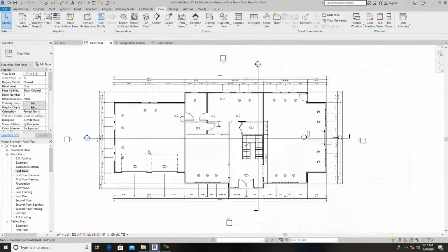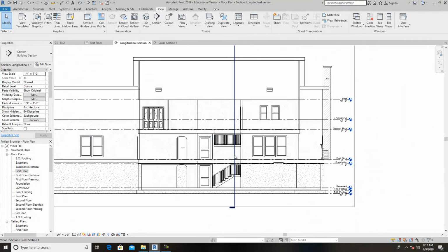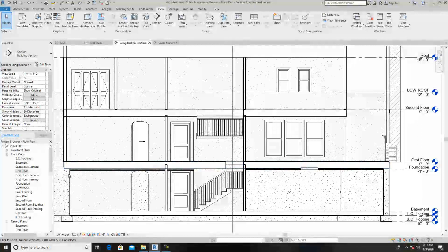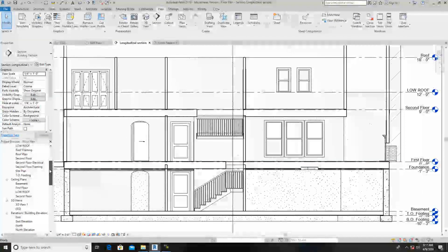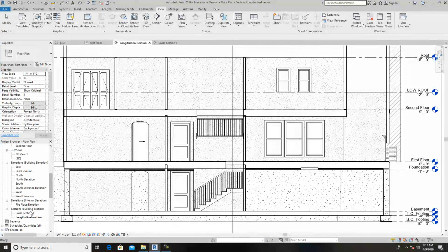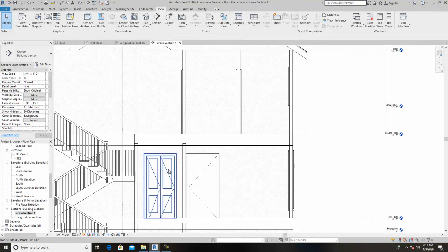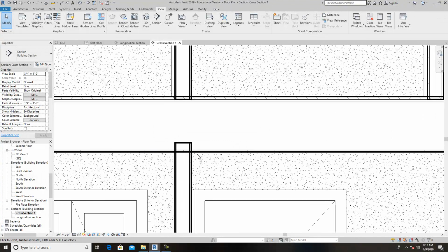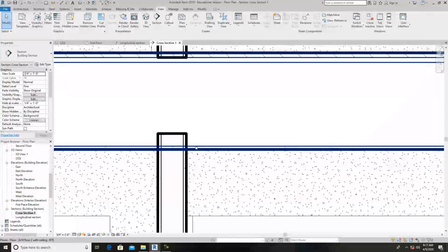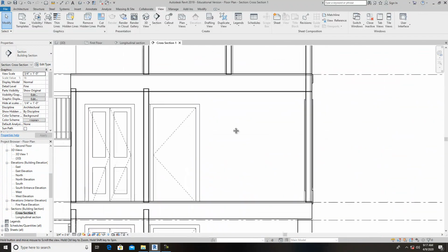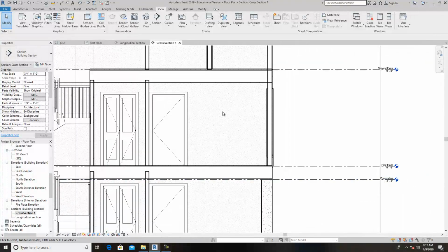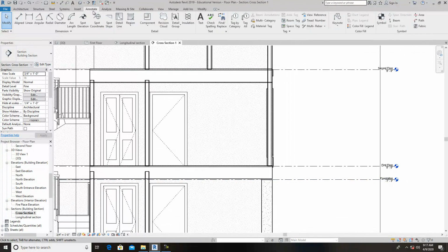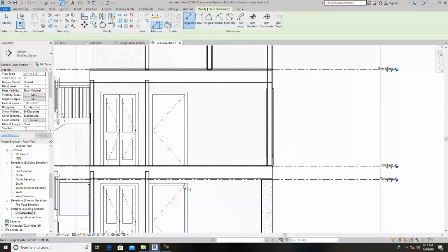And again, I want to go back in here and make sure when I look in here, there's that one. And we'll see how tall I need to make those. Let's do cross section 1. It needs to actually be coming up to the bottom, right here. So what I want to do at this point is, I know this is 0, and I want to do an annotate, and I'll do an aligned measurement.